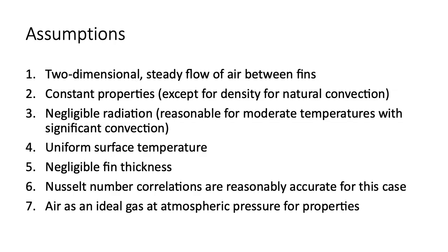Our fourth assumption is that the fin surfaces are at a constant temperature. Our fifth assumption is that the fin thickness can be neglected in comparison to the fin spacing in our calculations. Our sixth assumption is that we can obtain reasonably accurate convection coefficients using ideal Nusselt number correlations. Our seventh assumption is that the air is an ideal gas at atmospheric pressure, which will be used to look up properties. Clearly, these are some significant assumptions, and we should only expect an accuracy of about plus or minus